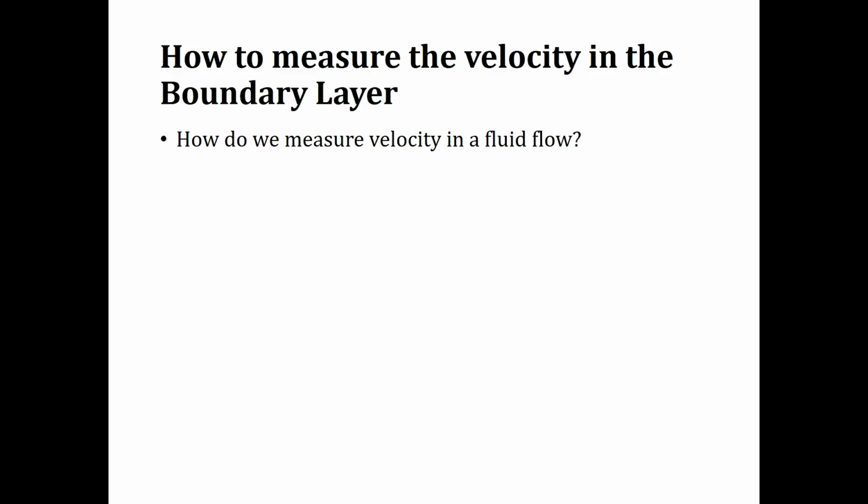So how do you measure velocity in a wind tunnel experiment or in any moving air experiment? How do we actually physically measure the velocity of air? The speed of the fan? Not quite, because how do you know that the fan is actually producing the velocity, the flow through the section that you want? Yes, a pitot tube. And what does a pitot tube actually measure? Pressure, yeah, okay. So we measure pressure, and then we use Bernoulli's equation to find the velocity.